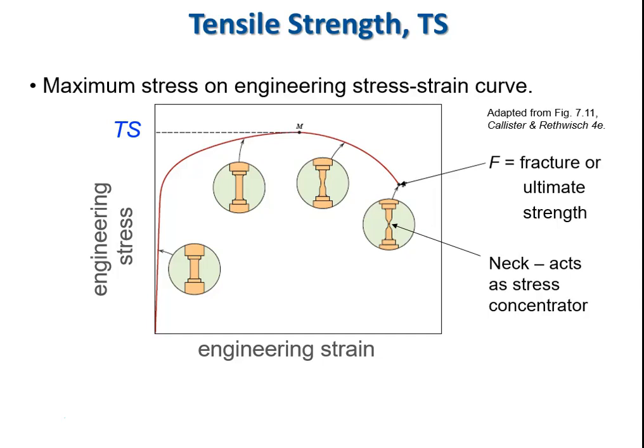So this gives you an example of what a side view of a uniaxial tensile bar, a metal specifically, would look like if we put it into controlled displacement and we measured engineering stress over engineering strain. So starting at the left-hand side of the curve, we're going to load it up. It's going to deform elastically along a straight line whose slope is defined by the Young's modulus. At some point we're going to begin to yield. We're going to move dislocations in that material, and we're going to deviate from that steep straight line, and the stress strain curve is going to bend over.